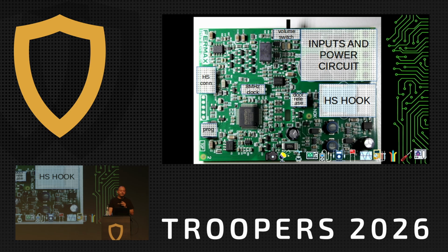Now, then we have these 3 nice packages, right? 8 legs, 4x2. And when you see those, the first thing you think is, wow, let's dump some EEPROM. Well, looking at them, none of them starts with 24 or 25. All of them are actually op-amps, so amplifiers. Very, very disappointing, which means that the code that we're looking for is in the microcontroller, which is an ARM Cortex-M4 in this case, made by Nuvoton. Oh, and finally, there's another thing that attracted my attention. On the very left, there is a connector.